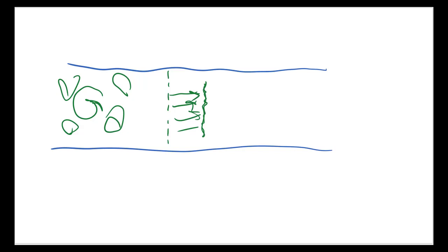But then as you get to the walls, the viscous forces dominate, and you get a sudden drop-off. The fluid velocity is fairly uniform for a large portion of the fluid going through the pipe, and then as you get close to the wall, you get a very distinct and very quick drop-off due to the no-slip condition. You probably looked at that a little bit in fluid mechanics, but there are just two very distinct profiles. The laminar profile is parabolic, and the turbulent profile is almost rectangular with very rapid drop-offs, high gradients of velocity close to the wall.